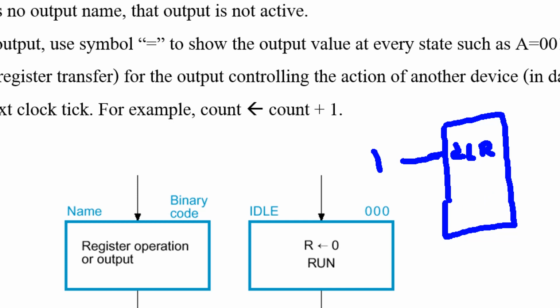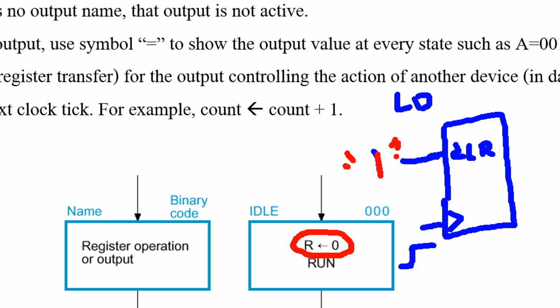For the design, normally clear or load is synchronous, clock synchronous control. Namely, it must wait for the clock tick to operate the load or clear action. So this just applies the control signal to make the clear, load, or enable signal become active.